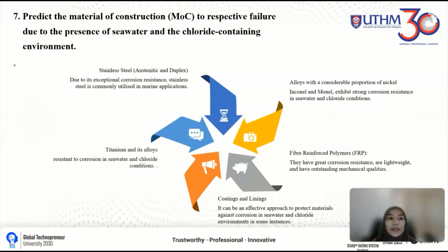So I would like to present question 7, which is to predict the material of construction (MOC) to resist failure due to the presence of seawater and the chloride-containing environment. So firstly is stainless steel, austenitic and duplex. Due to its exceptional corrosion resistance, stainless steel is commonly utilized in marine applications.